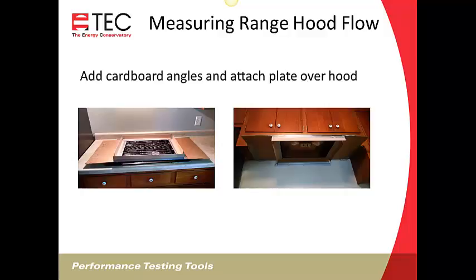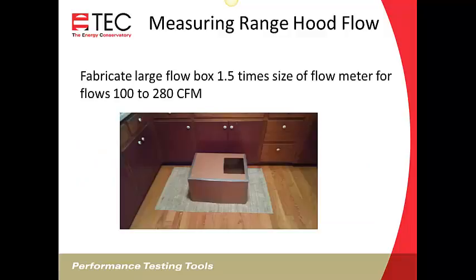I recommend doing this if you've got some of that kind of material around and you're using the same size box all the time to measure airflow. You've got that box that you're using that's 1.5 times the dimensions of the exhaust fan flow meter to measure bath fans that are over 125 CFM. You can also use it in this application, so you can have those angled pieces with you to make that more durable and easier to make a connection.